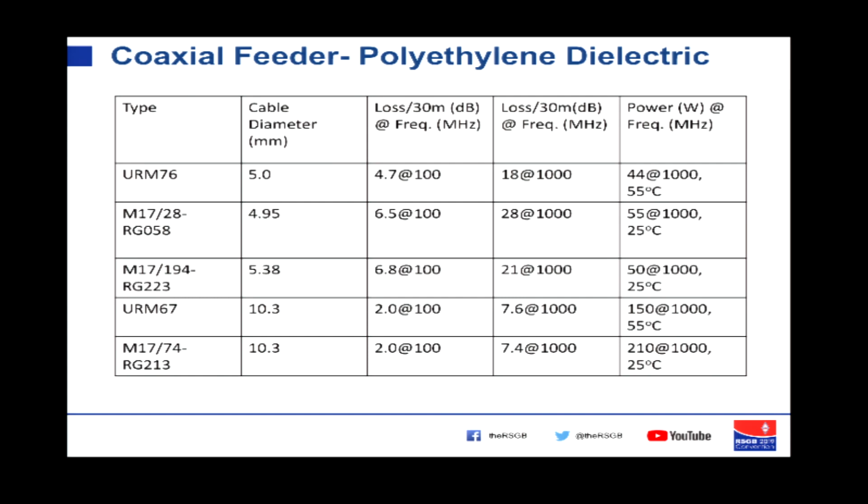used to call RG58, but watch out, because all RG numbers as such, if you just get a cable that says it's RG something, it has no meaning anymore, because that standard is discontinued. So anything can be called RG213, anything can be called RG58, and frequently is. If, however, it is M17/28-RG058, and it has the right supplier on it, it might actually meet the specification.